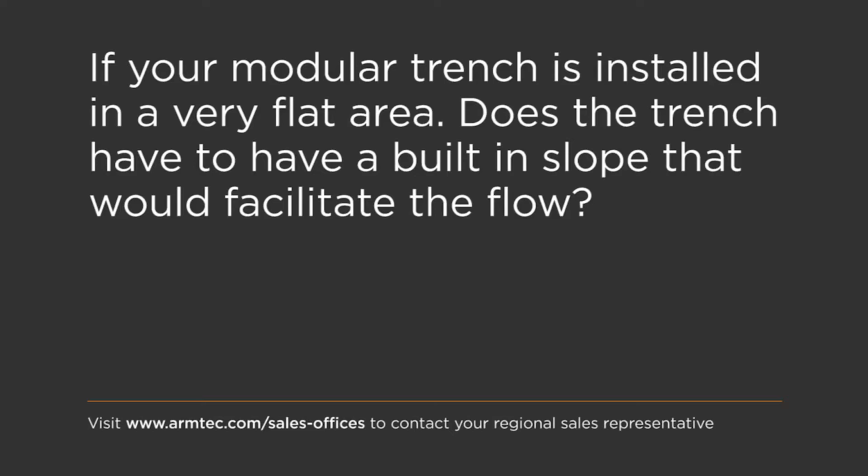at a larger product. What can be done is a step-fall system, which is a better alternative to a built-in slope, in our opinion. So basically what you do is you choose a shallower system connected to units that have a deeper invert. This installation will create steps which create a gradient similar to a built-in slope. But this will be used mainly when you have long trench drain runs.